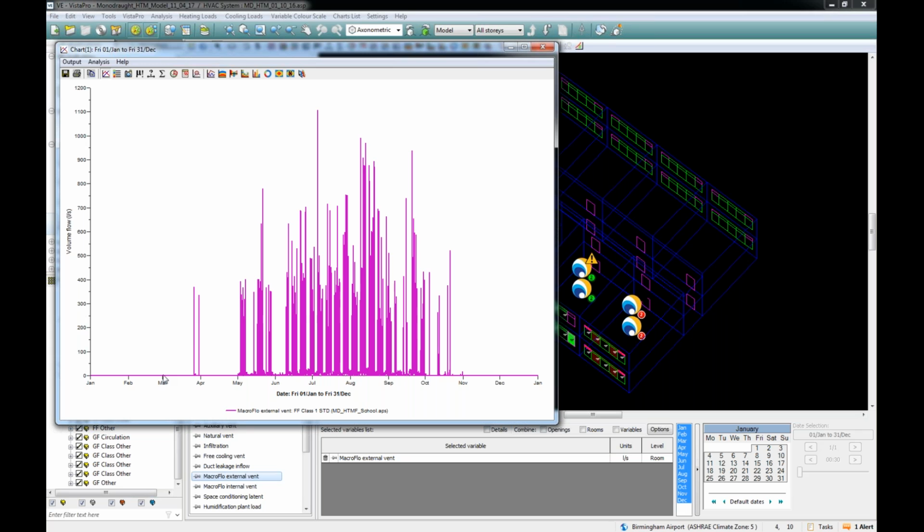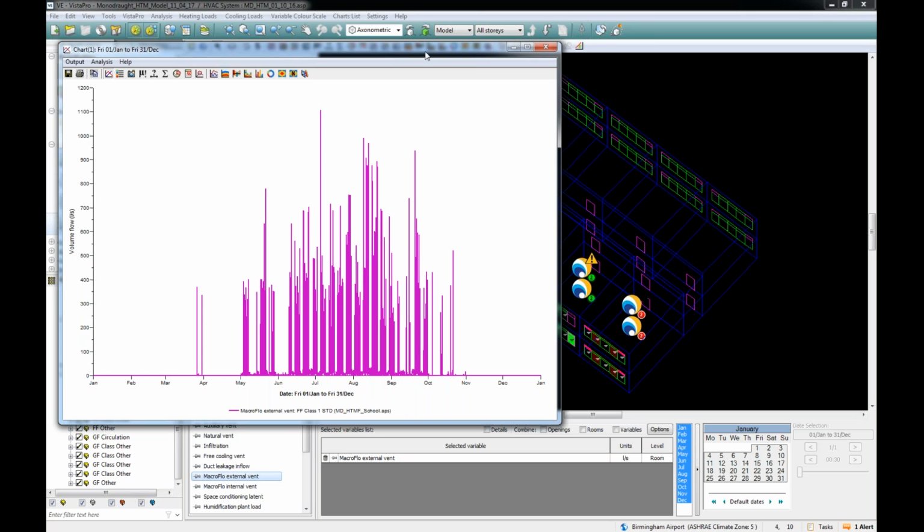Although you can see down here at the end of March we've got some openings, and also in October, because within this we also have the external temperature set point. So if we do experience warm weather during the winter months, which you might generally expect around late March, early April, and also into October, then we can automatically include the natural ventilation air supply.